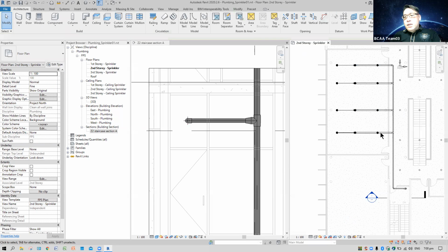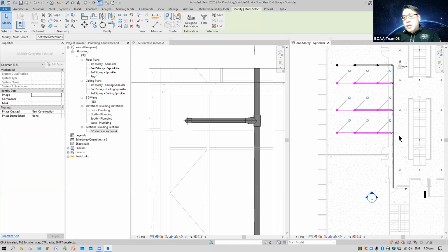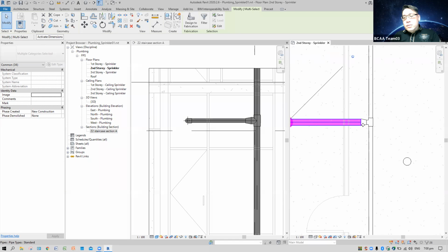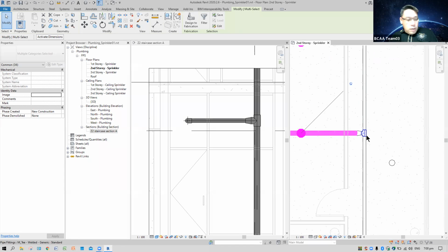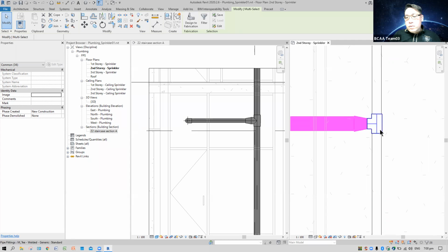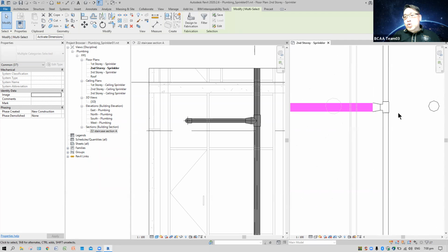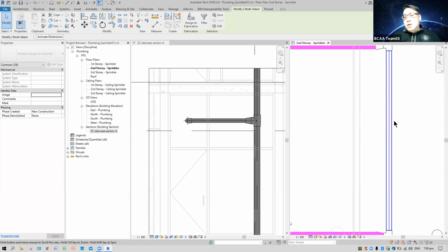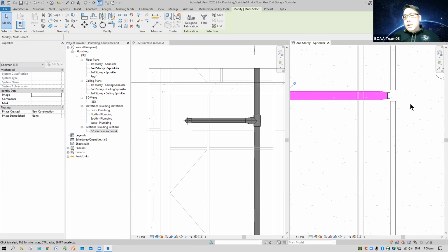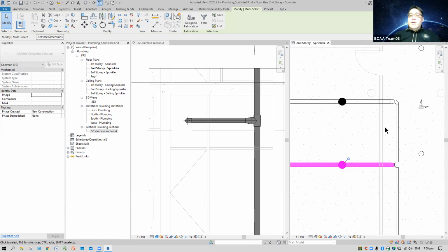As for this piping here, these are all wrong, so I'm going to delete them away. Careful, don't delete the fitting away. This one you can delete. Okay, so control key, you can pick this. Careful, sometimes from far it's difficult to select, so you zoom in. Because all this connection default is all wrong. And I also want to show how easily we can get it connected. This one I can't delete first because I need to extend out. If you extend out and delete away, later this joint doesn't work. There are a lot of funny tricks here. You just got to be careful on it.